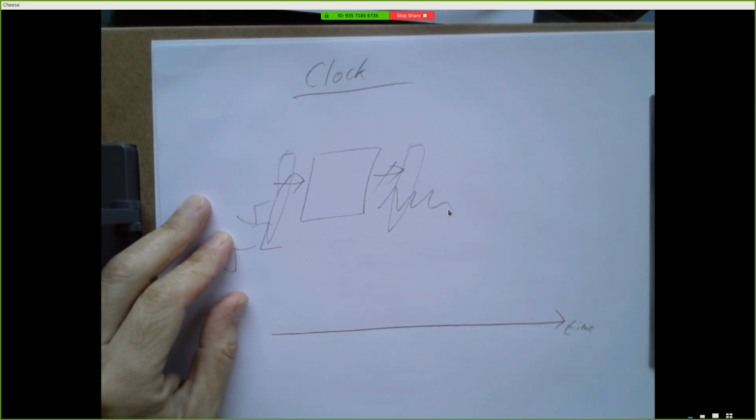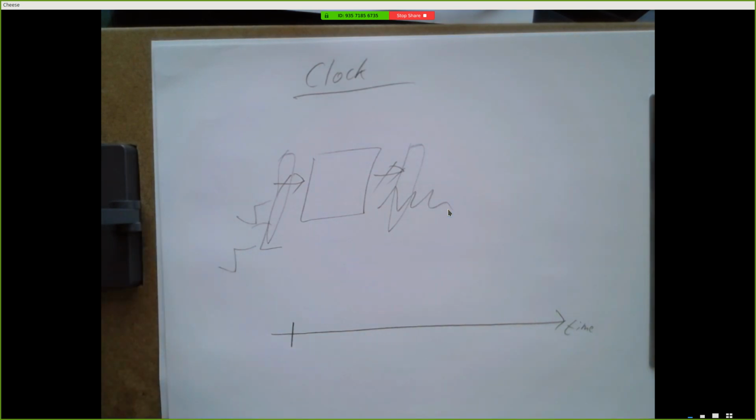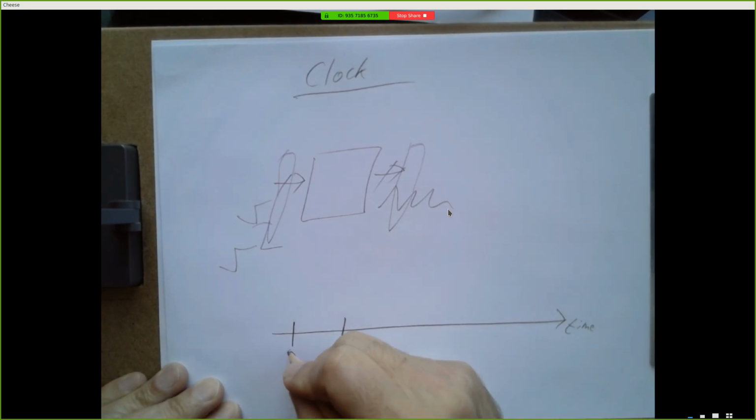So the idea is we're going to introduce a clock into our systems. And every time this clock ticks, inputs are going to change. And as soon as those inputs change, outputs might start to change. And temporary values in between the inputs and the outputs might start to change. And things might get glitchy and you might get a bunch of noise. But eventually things will settle down. And they should settle down before the next clock tick. So that when the clock ticks, we know that all the outputs we're looking at that moment are valid. And the idea is we only pay attention to things when the clock ticks, not in between.